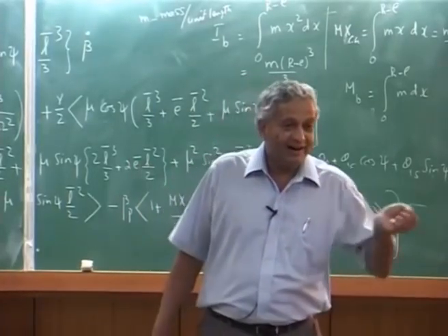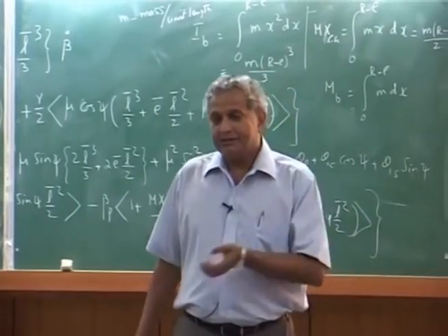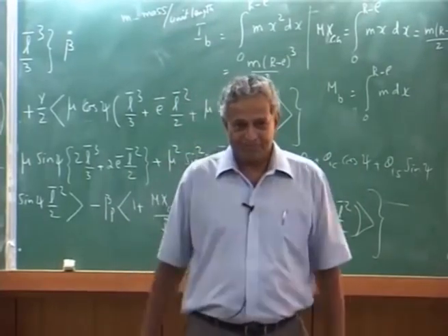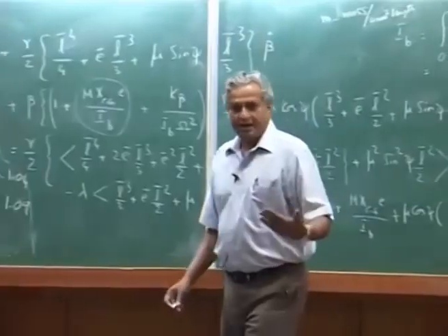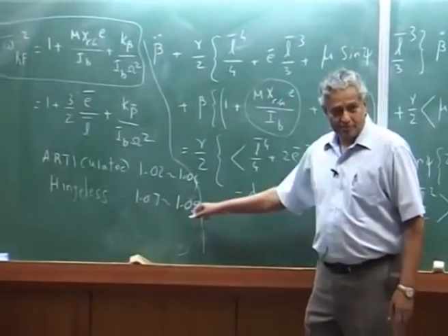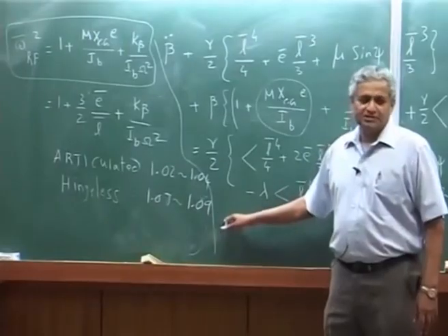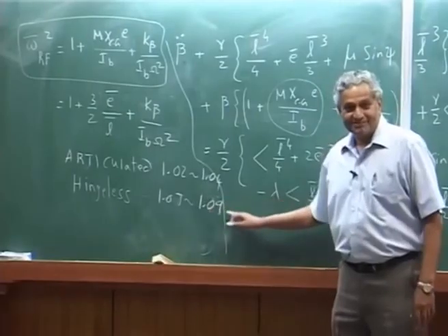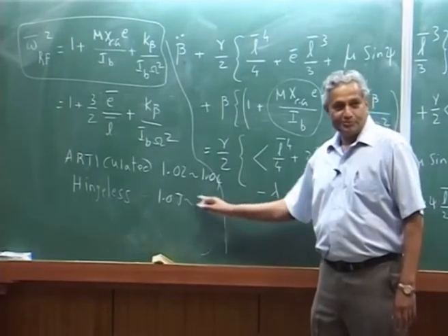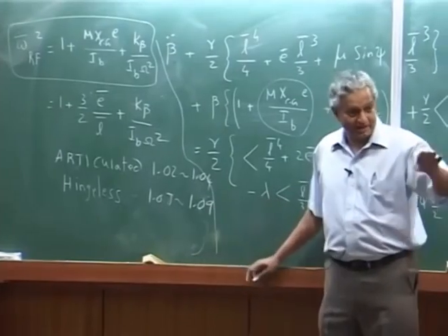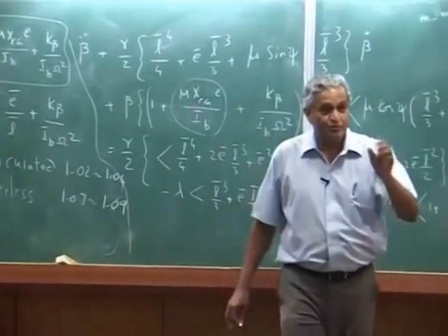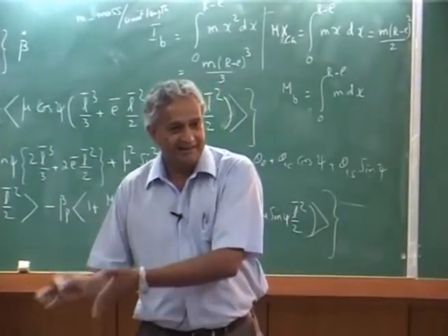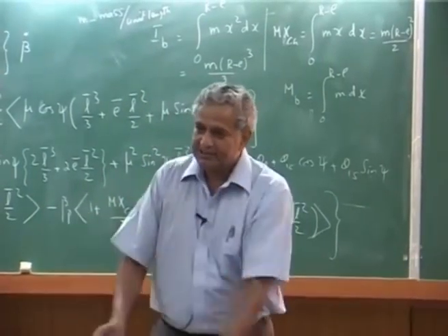That means, if you have a higher flap frequency, you will get a higher hub moment. That means, the pilot can generate more. Now, how much higher can you go? Then they will say it becomes too sensitive. So, they try to keep it only maximum in this range, do not go too high, otherwise higher flap frequency, higher moment, higher vibration. So, you will find the problem is, if it is hingeless, your vibratory loads also are higher.